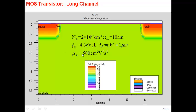The channel mobility of electrons in the channel is right now being assumed to be constant, 500 here, right? And so this is the structure of the MOSFET, and at various points I'll show you results obtained from simulation for this particular structure.